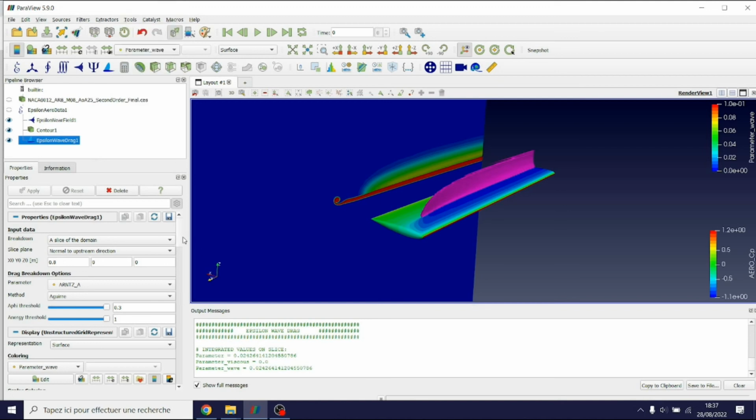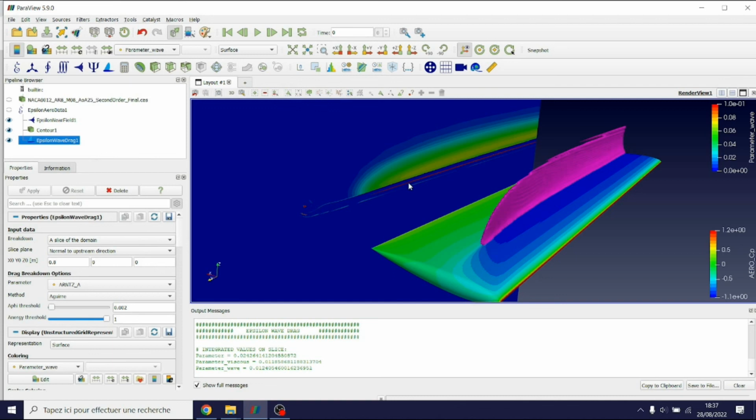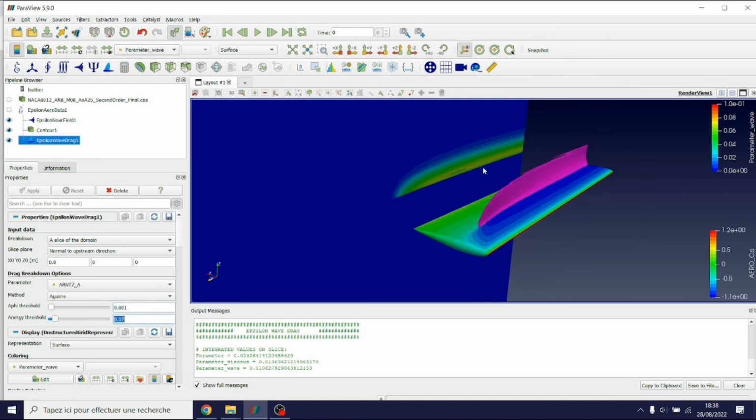Now that everything is ready, I can start sliding this downwards, and I will visualize just the wave component in my case. So I start sliding it, and I will see that at some point it may disappear, or not. You'll see it start cropping here, just very small values. Here's the entire wake in red, and now if I decrease, I start seeing that the wake is actually decreasing. I can maybe put that by hand. And you can see that here we have a red line in the middle of the viscous part, and we can get rid of that by decreasing the second slide bar. And okay, just a little bit more. And now we have gotten rid of almost everything. Yes, we have separated the green part corresponding to the shockwave from the viscous part that's here.